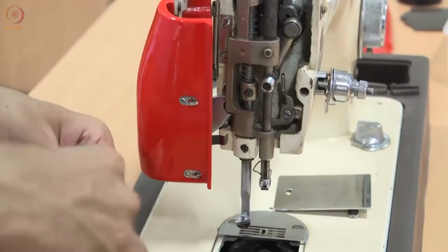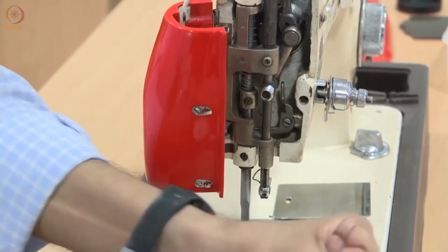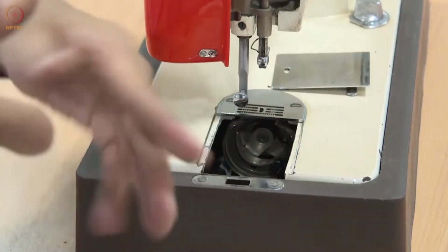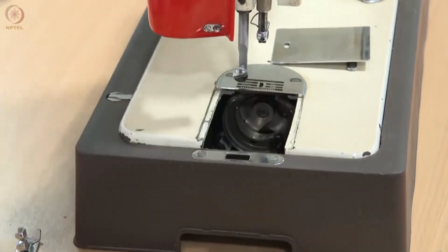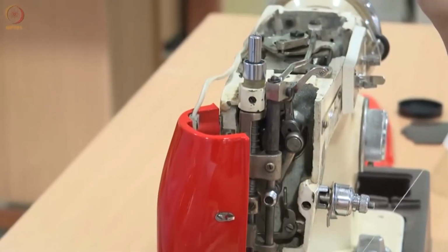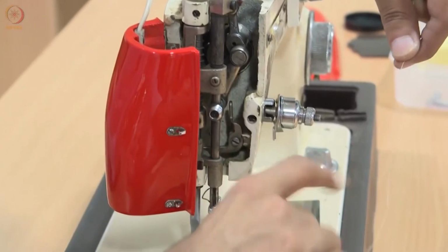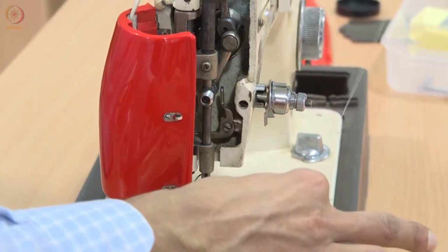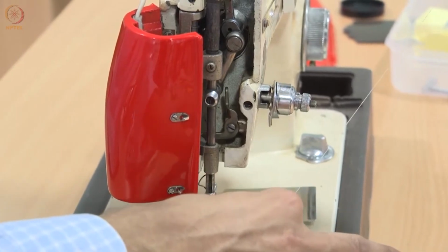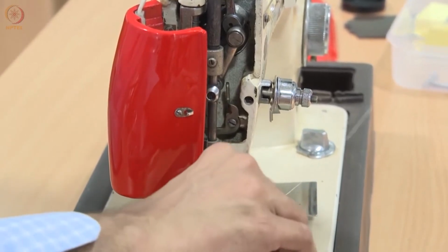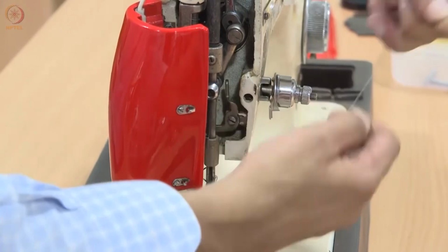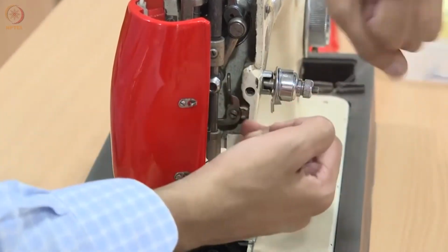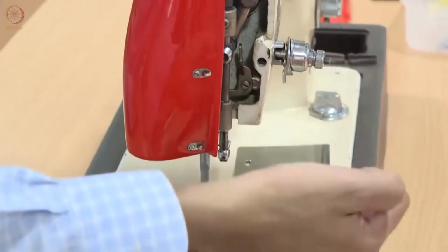thread. If the thread is too taut, it will break, right? If I simply put the thread on a spool and feed it into the needle, it needs a little bit of tension in the string. So something has to offer some amount of resistance, yet at the same time, the resistance should not be so much that if too much pulling force is applied by the thread feeding mechanism, the thread will break.